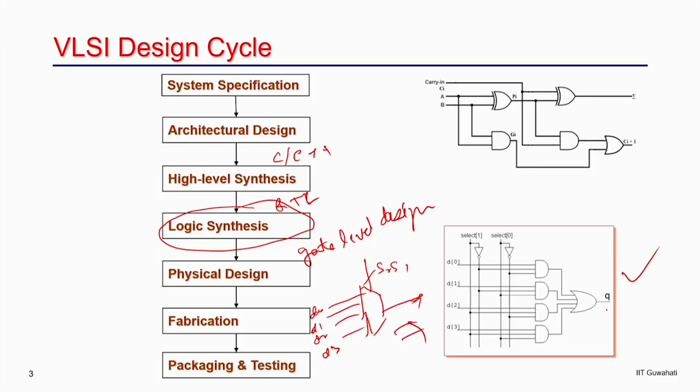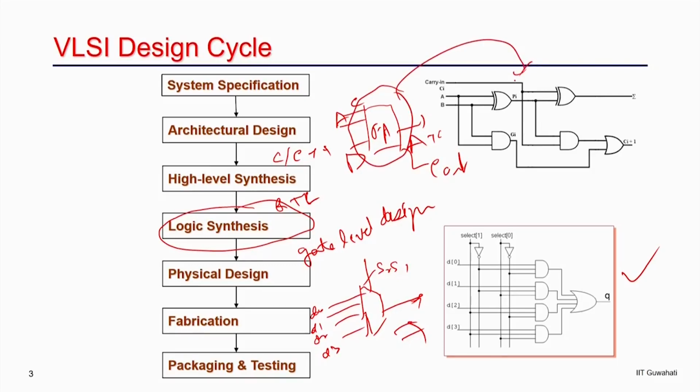Similarly, suppose you have a full adder, right. It takes inputs A and B, and there is some carry input C, and it computes A plus B, and produces some carry out. So we can replace this RTL module by the equivalent gate level design. Yes, this is a full adder circuit. This is for 1 bit, and if you have say 16 bit or 32 bit, the same block will just be chained, with the carry output feeding the next carry input.